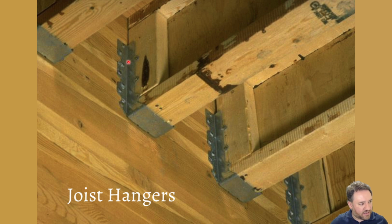And you can see the way that this joist hanger works. Obviously, it can't come inside the flange to connect to the web. So actually, you're required to provide a blocking here so that we can have the joist hanger connect to the blocking. And now this blocking with the hanger together prevents the twist that would be possible otherwise with this I-joist.